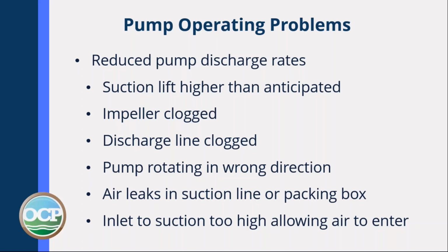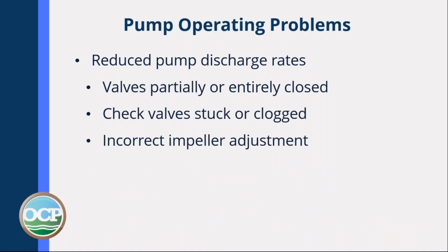Make sure there are no air leaks in the suction line or the packing box. Your inlet to suction may be too high, allowing air to enter the pump. The valves could be partially or entirely closed. Check valves could be stuck or clogged. And the impeller adjustment could be off, or if the impeller was recently replaced, they may have put the wrong size impeller in.